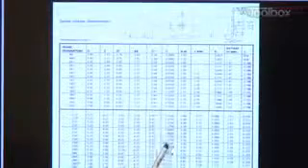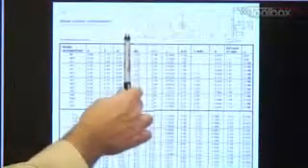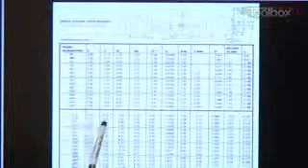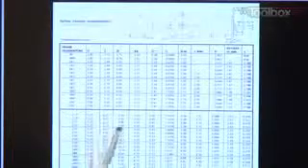This is a standard chart that you would see used for the frame size. What you end up with is a chart that has different columns. Every column is a mechanical dimension on the motor. Accompanying all of these tables, these charts, will be a drawing of that motor showing what each dimension means. Like shaft height, for instance, is drawn out, hole patterns, those kinds of things. If you go down and find your motor, you would find every dimension. There's the 215T, every dimension that's called out on that motor.